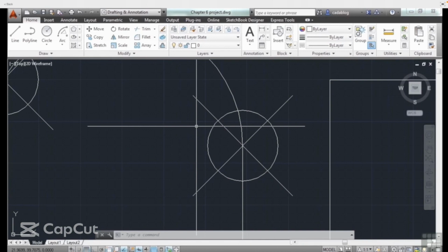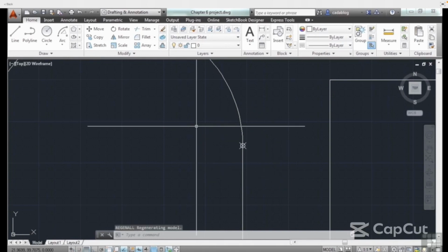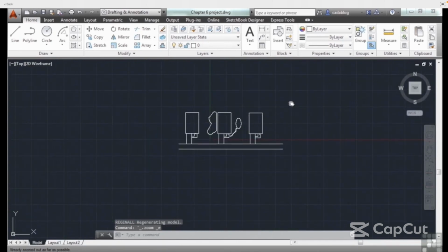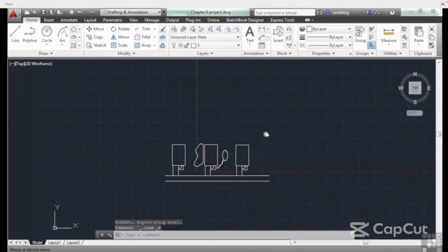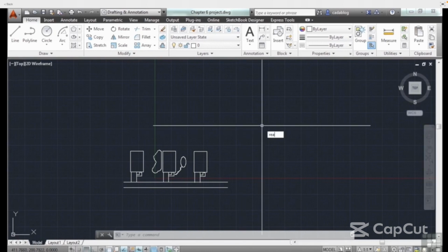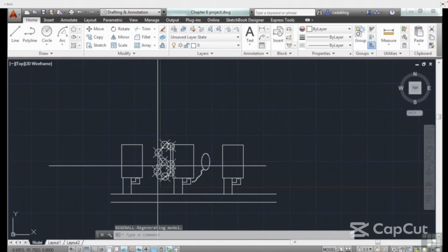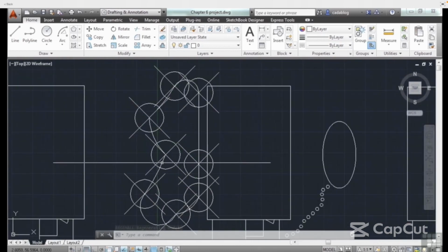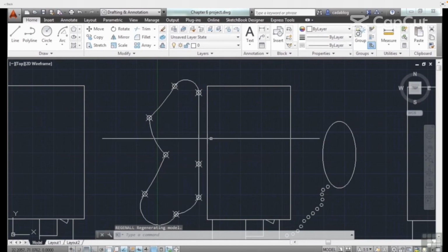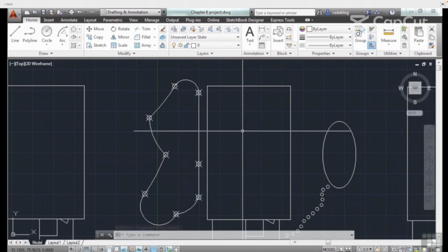And that happens. When it does, just type in REA for region all. That will clear it up. We've seen that before when we've zoomed out and started panning and just can't pan anymore. Type in REA for region all, and it will fix that. It will also re-render your points so that they'll be in the proper size, assuming you've set them up to be a size relative to your screen.